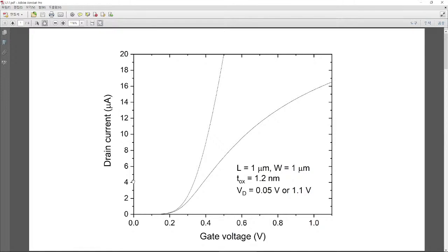So usually if we have a higher and higher gate voltage, unfortunately mobility is reduced. If we had constant mobility, then we would have this beautiful behavior, a straight line, but unfortunately we have reduced current. So if I ask you why we have smaller current than expected, the reduction of mobility is the physical origin of this undesirable behavior.